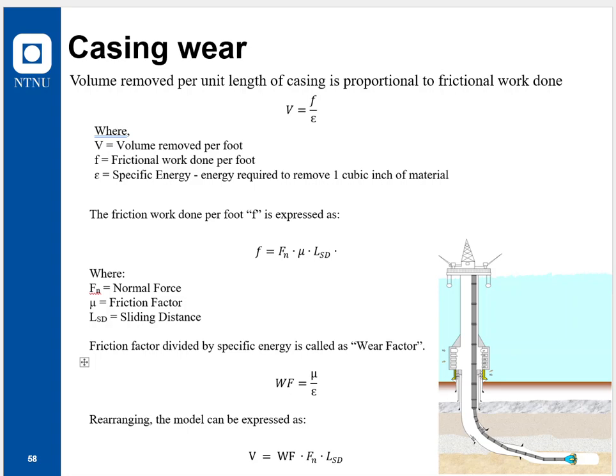The wear factor is a bag of so many factors, like the type of mud, temperature, how much cuttings would be in there, and so on and so forth. But in the modeling software, as a rule of thumb, we put in 5 for the wear factor in our simulations.